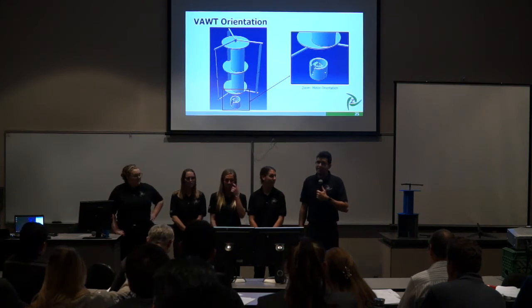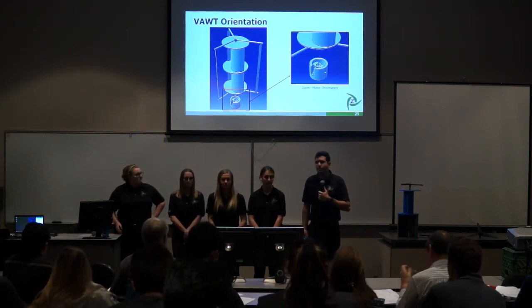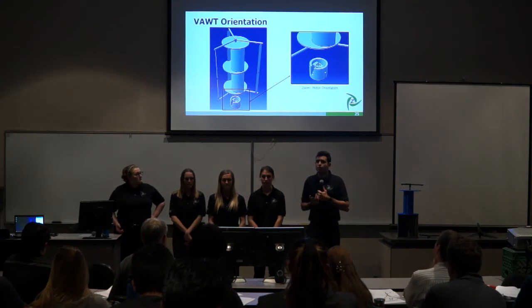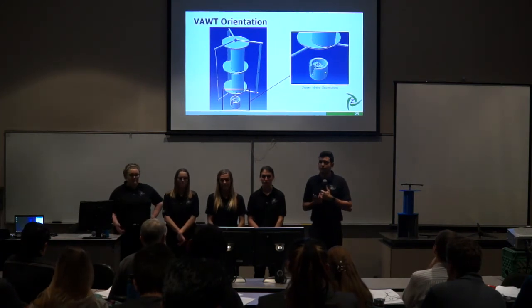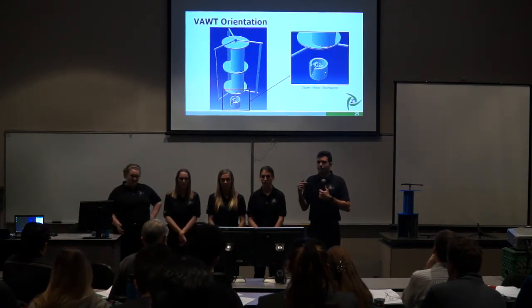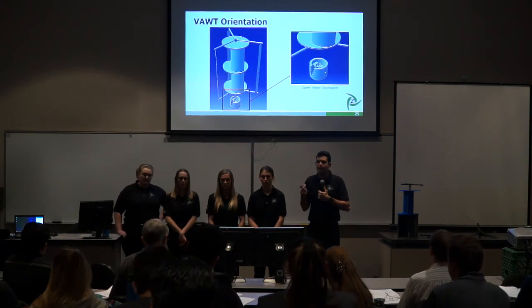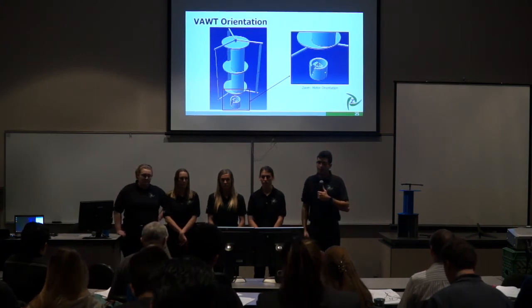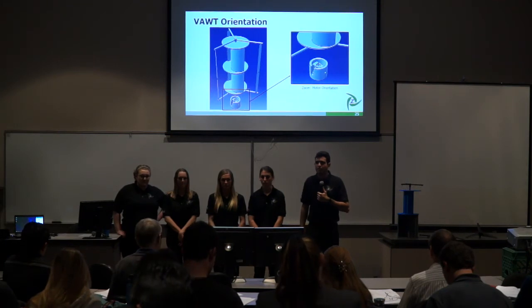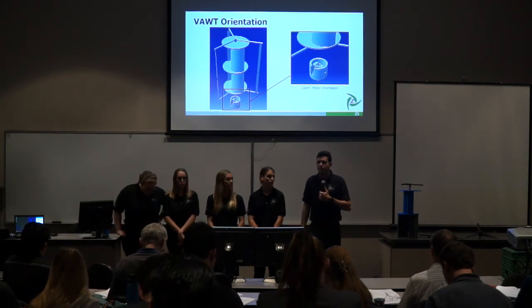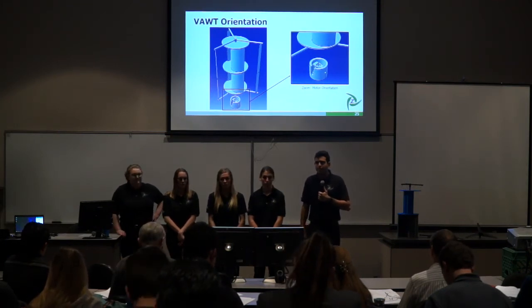So the design that we currently came up with is actually because the motor already has holes going through it with screws in it, so it's just a simple solution. Get a longer screw of the same thread and just make it go through the plastic itself and just put a nut on the other side. So it's using the already available space inside the motor.